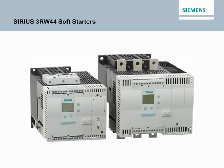Sirius 3RW44 soft starters make soft starting and stopping attractive for demanding applications and combine a high degree of functionality and extensive diagnostics. 3RW44 soft starters are available for operating current up to 1214 amps at 40 degrees Celsius. A backlit display with 4-key operation simplifies the process of changing parameters.